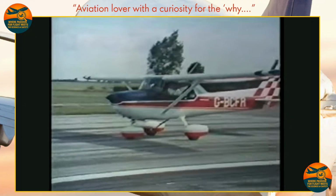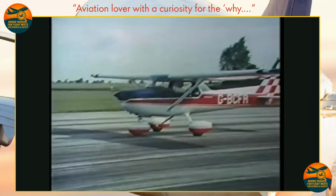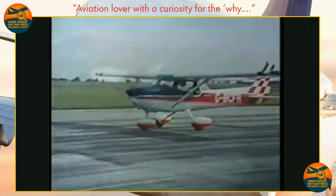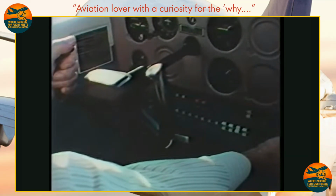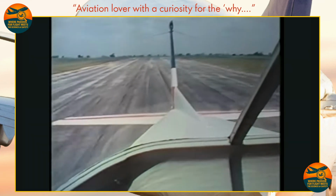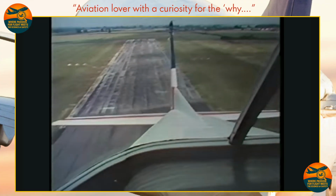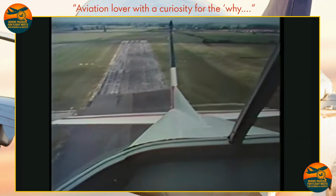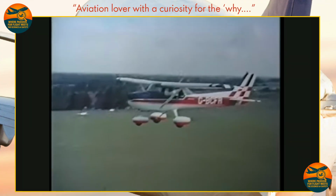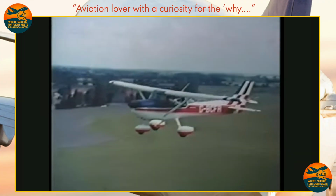The pilot opens the throttle and the aeroplane accelerates. As flying speed is reached, he pulls the control column back, the elevator rises, the tail goes down, the aeroplane lifts off and rotates into the climb. The elevator returns to the neutral position. What the pilot has done is to increase the angle of attack so as to give the wing the extra lift it needs as the aeroplane rotates.